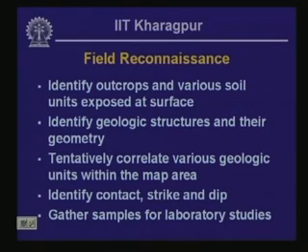The activity also includes, one must also include when carrying out reconnaissance, the information about the dip of these features or different types of structural landforms, the outline of different types of structural landforms that may be there within the area that is being mapped. In addition, one will have to identify tentatively the age of different geologic units within the map area.